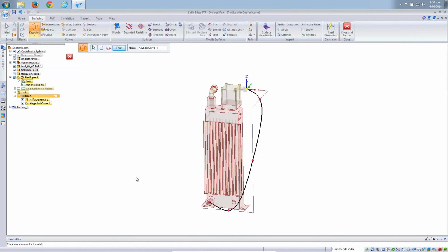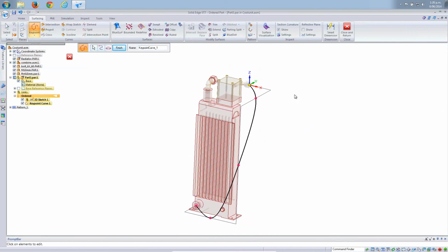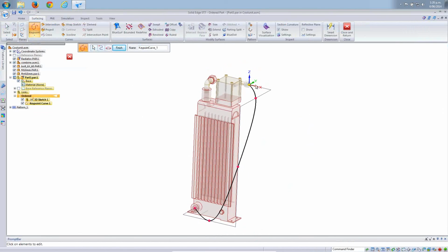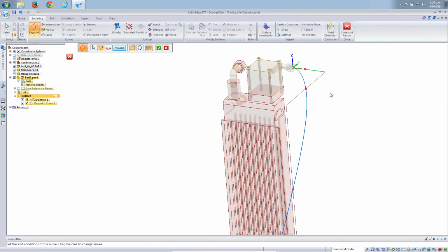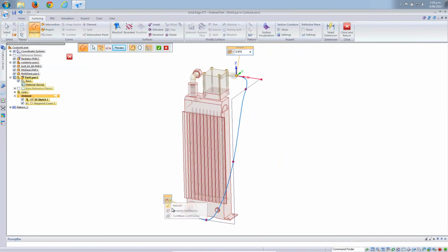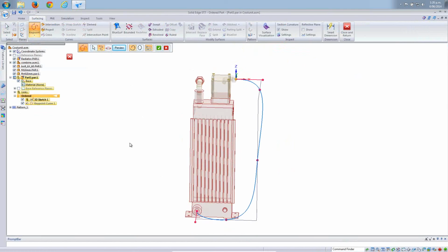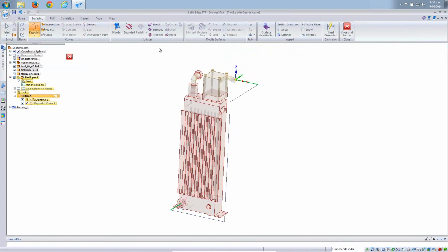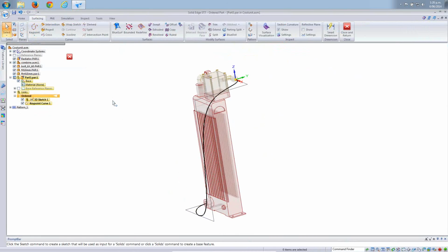Not too bad, but we need a little bit more control. This spline needs to be tangent, really, the start and finish tangent to the ports that it's supposed to run into. So there are some nice controls that they introduced in ST6. Not so much the control, but these little handles, they were introduced in ST6, which really just make this process a lot easier to achieve. So I've got little drag handles. I can set how the tangency works to create this path. Tick the box, finish, and we're happy with that.